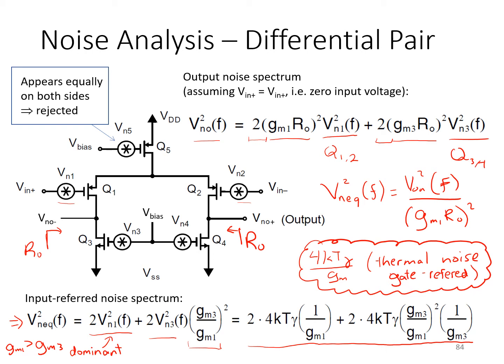So again, this both maximizes the gain, the bandwidth, and minimizes the noise contribution of the input diff pair, while at the same time minimizing the noise contribution of Q3 and Q4 without negatively affecting the gain or bandwidth of the stage.